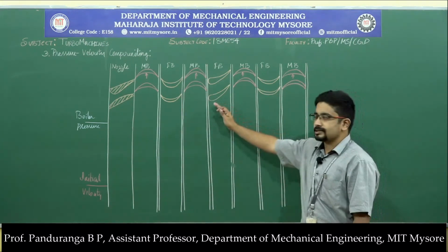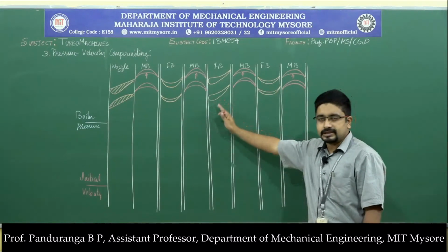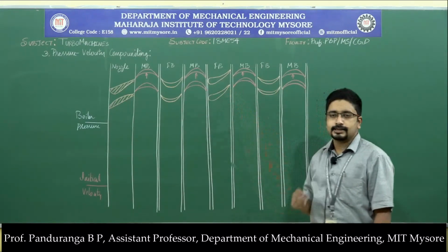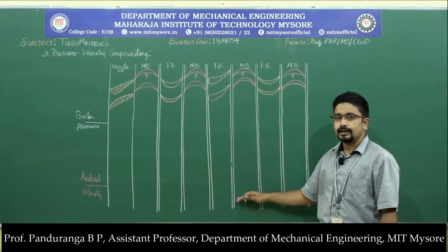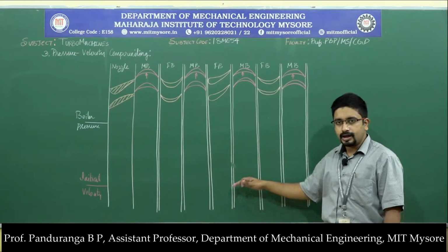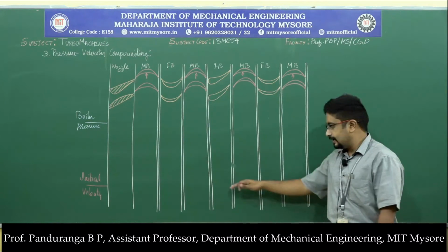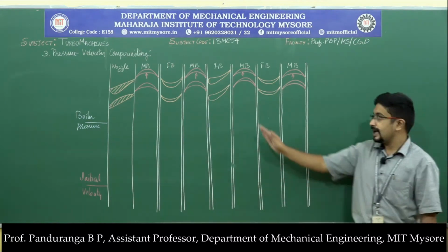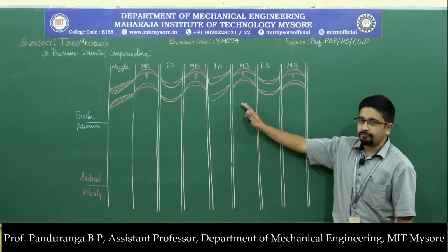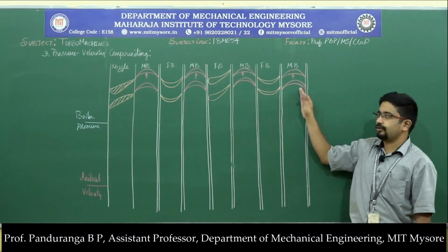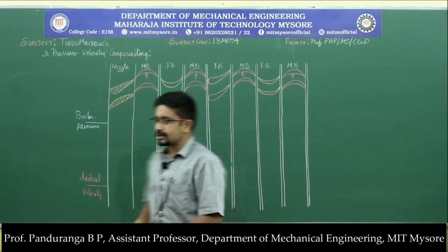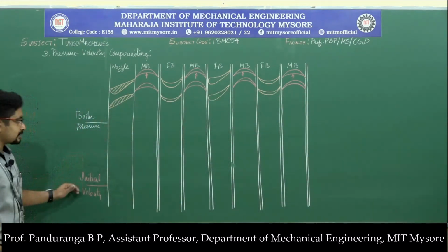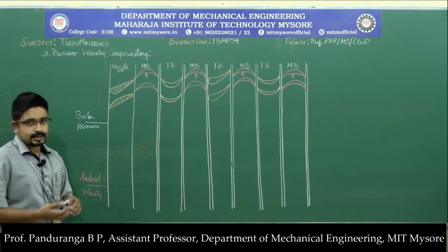So as the steam passes through this blade, the fixed blade, which is aerofoil in shape, the pressure changes and attains the atmospheric pressure or a lower pressure, and the pressure remains the same as it moves through the third row of moving blade, fixed blade, and the fourth row of moving blade. Okay. Now let us see the variation of pressure and velocity in different stages.